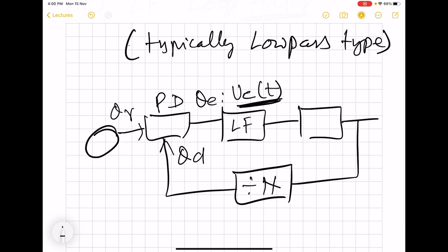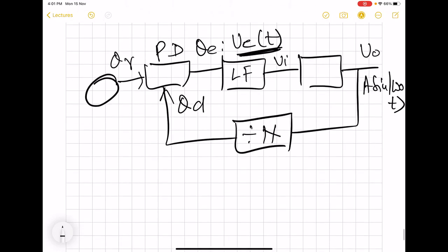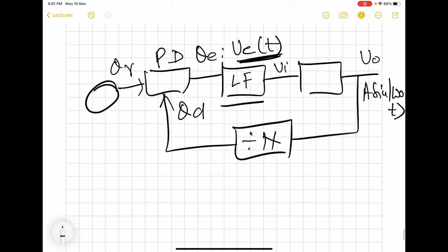And then that is fed to VCO, and then VCO finally produces output of desired frequency. And this loop filter has a role in deciding how fast this output settles to the omega naught, the stable frequency. So the transient duration is quite closely dictated by this loop filter.